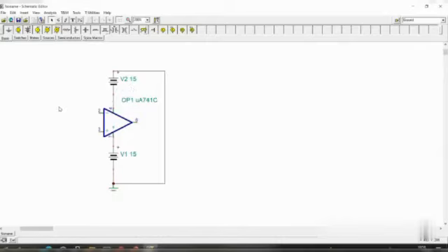Okay. So after that, according to the circuit diagram, I have already shown you the circuit diagram. As I know the circuit diagram, I am just drawing it. In that, what you have to do is you have to connect resistors, that is inverting mode. Okay, as it is inverting mode, 3 can be grounded. So here you can have 3 to be grounded, and also an input is to be given.